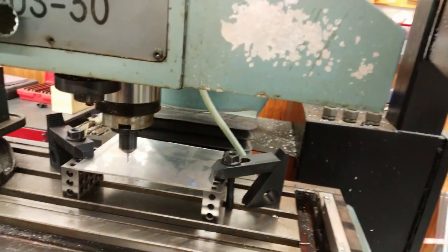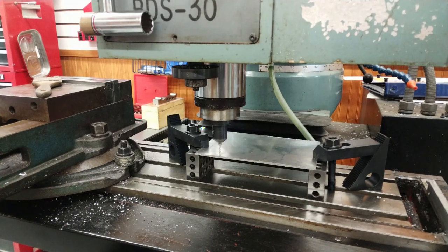So the next thing I would do is touch off my material to the top. When we set up the job, we actually specified that the stock was 4 millimeters thick, to give it a little bit of through cut depth. So what I need to do is touch off the top of the stock material at 4 millimeters. Then it'll start cutting down from that point, and it'll actually go through about 1 millimeter. So the final pass may not be actually necessary. I need to touch off the top of the material at 3 millimeters, which I've done, and I should be ready to start now.